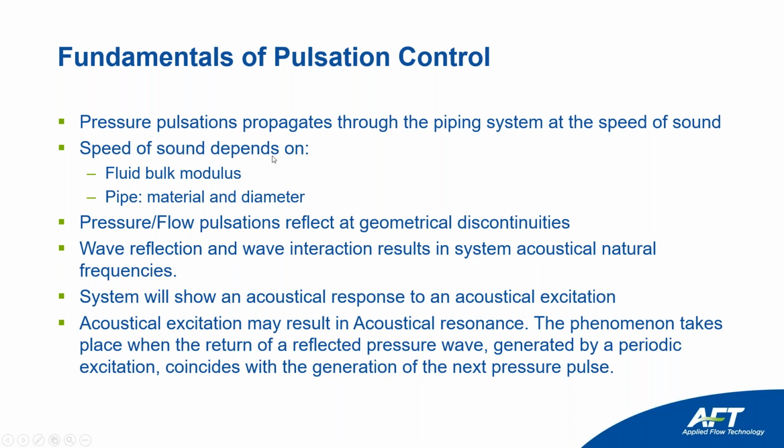Pressure pulsations propagate through the piping system at the speed of sound. Speed of sound depends on fluid bulk modulus and the pipe material and diameter. Also, the way the pipe is supported, whether it's buried or not, also influences the speed of sound.